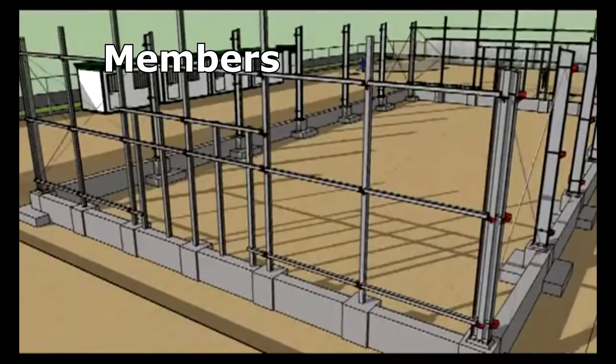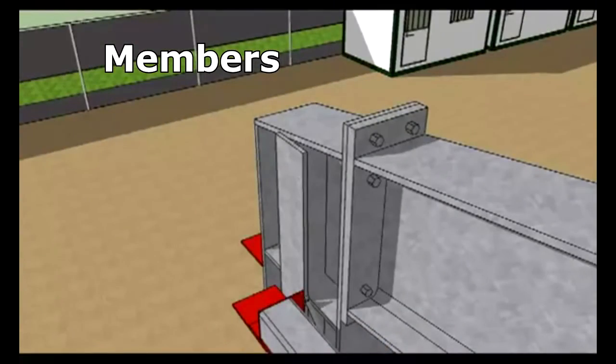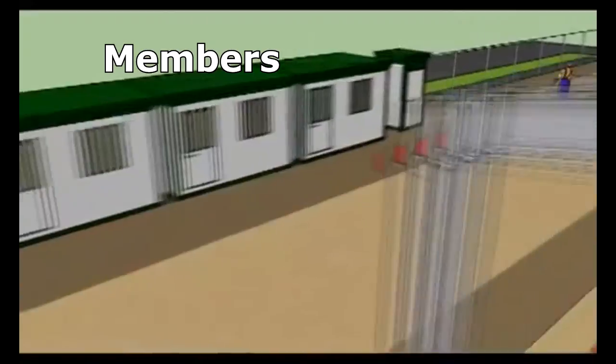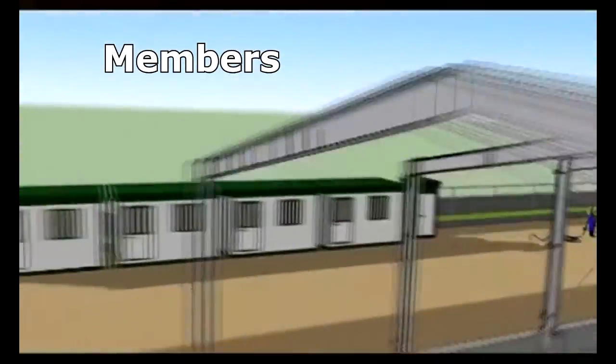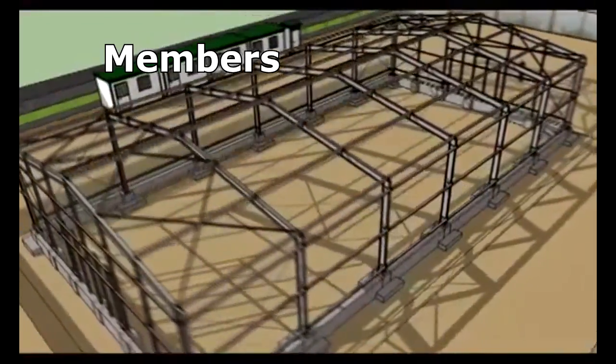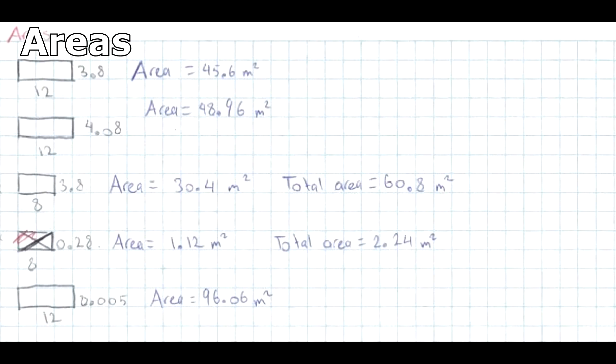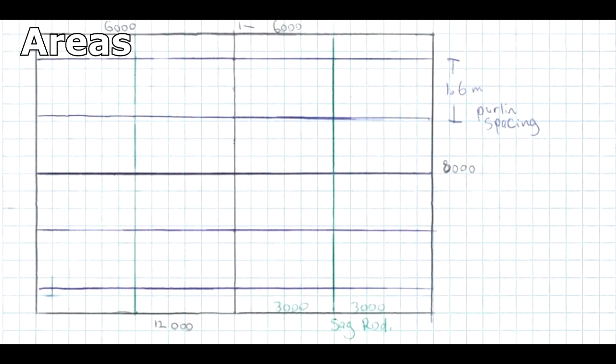For this project, certain specifications were provided to design the structure of a domestic shed, including determining the design loads, designing purlins, a typical sidewall girt, bracing layout and elements, a typical column, and a typical rafter. The areas are first calculated for the purpose of calculating cladding and insulation. Purlin and girt spacing is selected with a maximum spacing provided in cladding manufacturers' design tables.